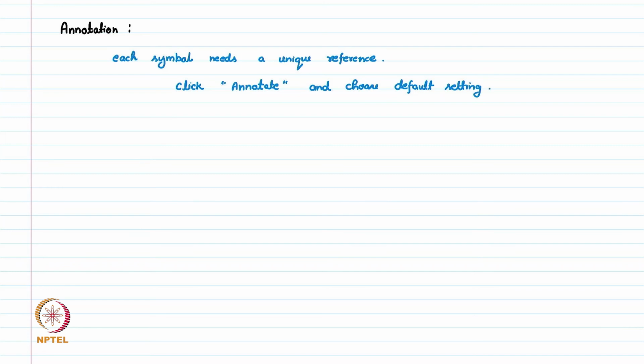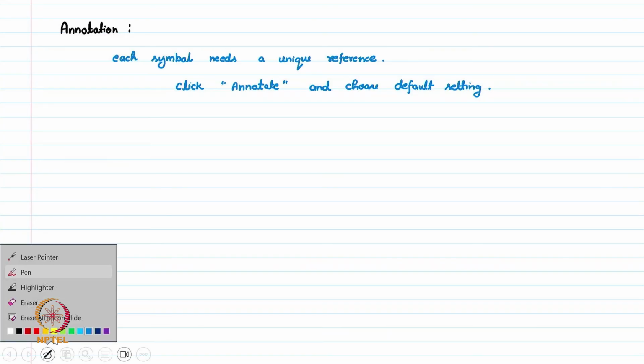By choosing the default setting, KiCad will automatically assign some reference to these devices. However, if you want your particular name, you can always change it in the annotation stage.